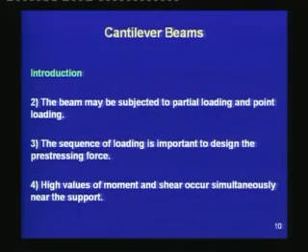The third important aspect is that the sequence of loading is important to design the prestressing force. During construction, the sequence of loading in a cantilever is important to design the prestressing force, and the prestressing force can be applied in stages to take account of the sequence in the loading.